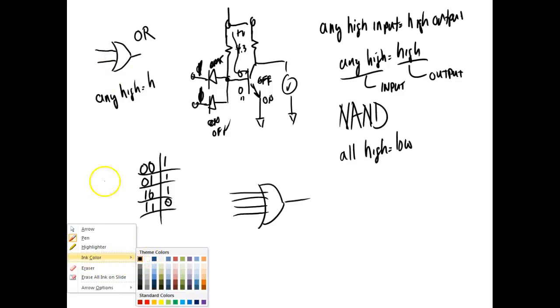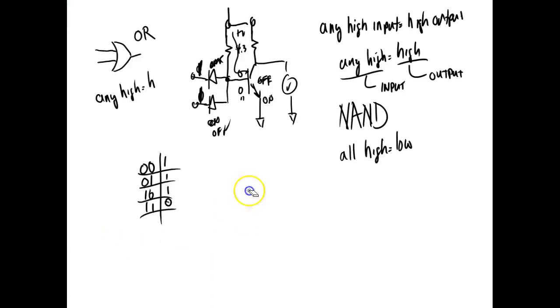So normally when we do truth tables and we learn symbols, we learn them with 2 inputs. But you got to understand, an OR gate's got to have a minimum of 2. Everybody understand that? A maximum of a lot. Of course, we're going to put them in standard packs. Well, if I take that OR circuit and run it into this little guy right here, this guy has a symbol. By the way, this is a type of logic. This would be called DTL.